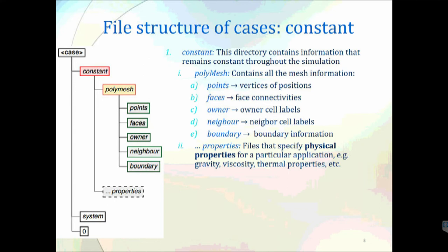Basically, these are generated automatically. I will explain to you how to generate these files automatically by defining just one file. Most of the time, for simple cases, you just need to define one file in OpenFOAM and run the blockMesh utility, and it will generate these files automatically.